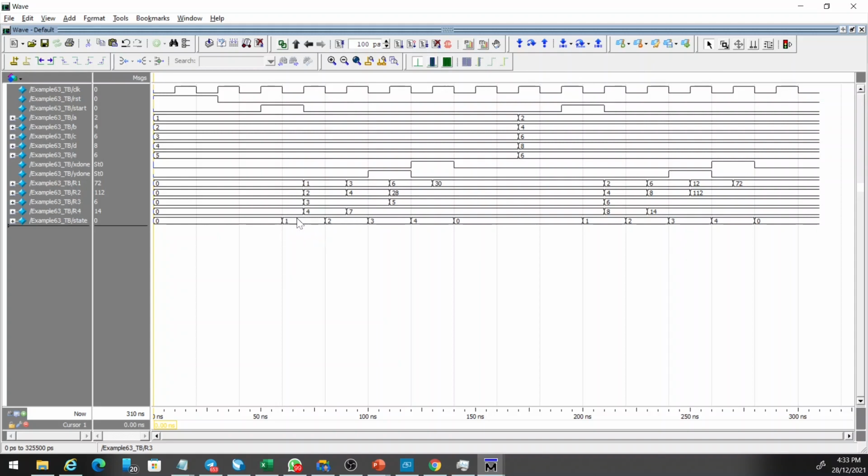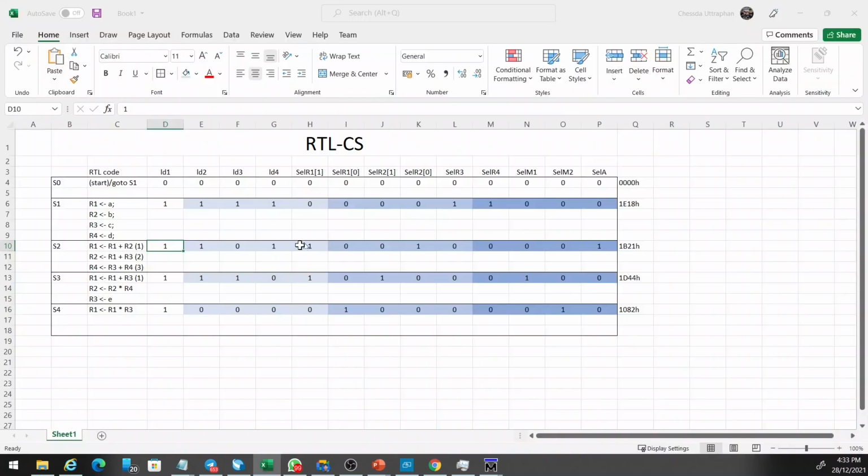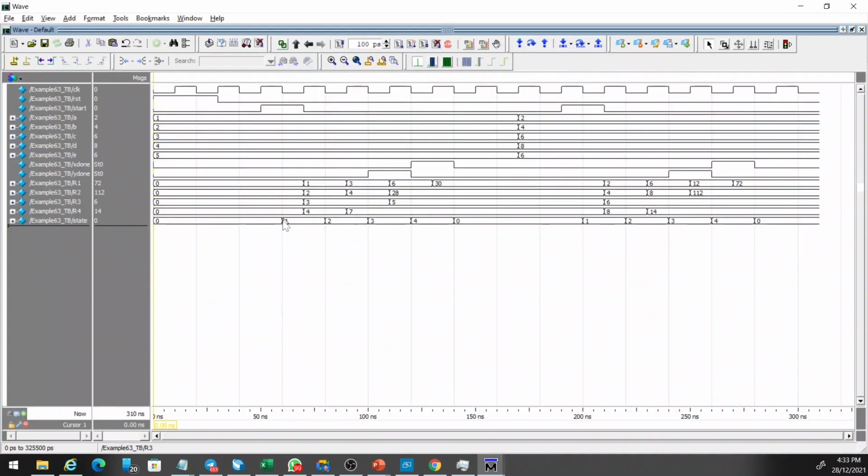Here we can see that we delay half a clock cycle before we can load the data. And because we set in our design that we load the data at the positive edge of the clock, the first negative edge, we change the state, right? The state is stable now. We load the data. So here we should be safe from any signal delay or whatever, right? So that's the reason why we have different clock edge flip-flops.